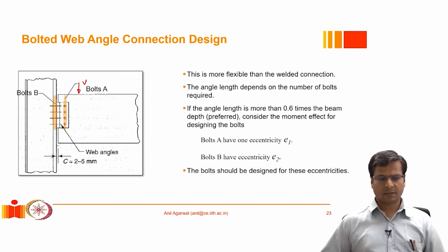Also, as we had discussed, when the beam starts to rotate because of the external loads, because of that rotation you will observe that there will be an additional shear force demand on these bolts. The top bolts will be pulled outward and the bottom bolts will be pushed inward. Okay, and that will introduce an additional force demand on these bolts.